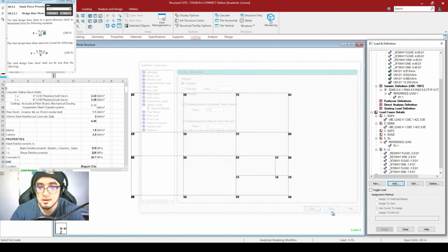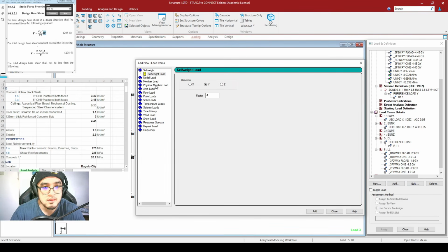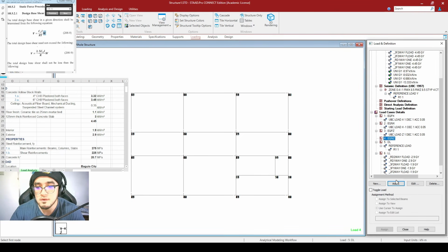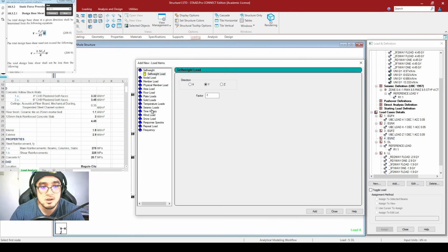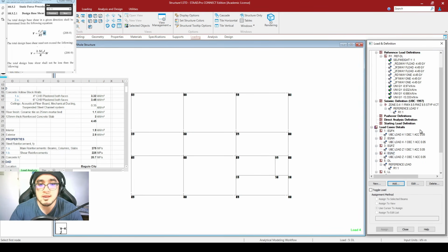Then add. So as per our z direction, click add. Then of course seismic loads. Then right now we would be clicking z direction here, then +1. So this is still 0.05, and this is now equal to 1. Then add. Then as for our earthquake load in the negative z direction, seismic loads, z direction, -1, this is 0.05, and this is 1.0. Then click add. With that, guys, we are already done in assigning our earthquake loads, dead loads, and our live loads. So there.